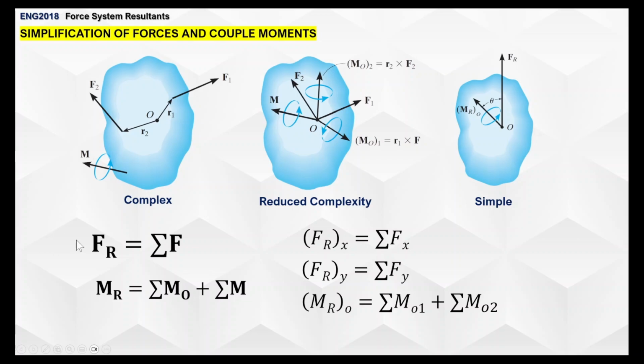So the magnitude of the force vector resultant is simply the square root of the sums of the squares of its x and y components, essentially. And if it's already expressed in Cartesian vector form, which we will be playing with later, all you have to do is express each force vector, force 1, force 2, in its Cartesian vector notation form, and simply do algebraic addition or subtraction, whichever is the appropriate sign for it.